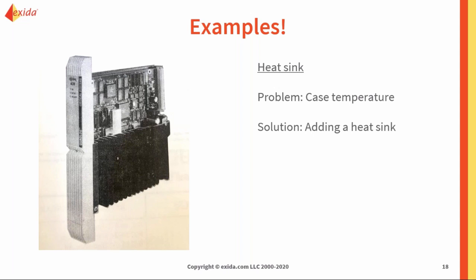This was seeing case temperatures of a microcomputer at like 70 to 80 degrees C. And that's normal or typical for these cases. So experts say that failure rates will drop significantly if these parts operate at lower temperatures. I've heard a general rule of thumb that they can be cut in half every 10 degrees or so.